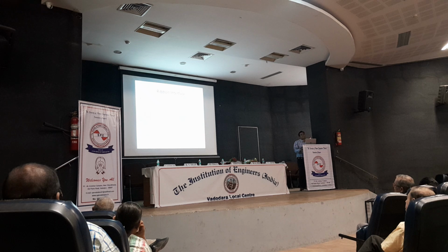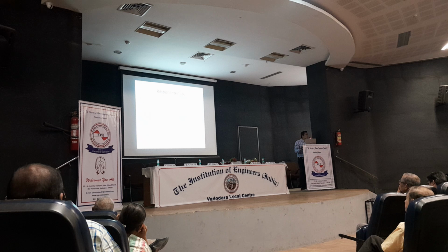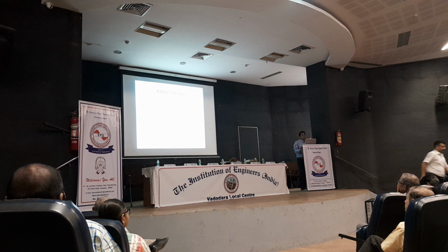So whenever we are dealing with this PowerWorld simulator, whatever drawings we want to prepare, we are going to prepare in edit mode, and whatever analysis we want to do, we have to do it in run mode. So when you click on edit mode, the drawing tab will be activated, and from that you will find the various components like your generator, your buses, your loads, your shunt connections, everything, and you can prepare a drawing as per your analysis requirements.